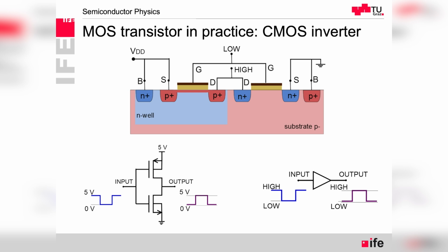But in this case, for sampling, we would like it to be small CS and small R-on. That gives low sampling time. So that also very much depends on what parameters for the transmission gate we have chosen. We would like large W over L. But then there is a compromise in what happens in the hold time.